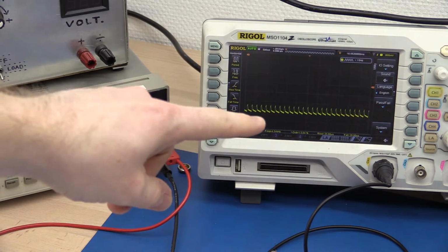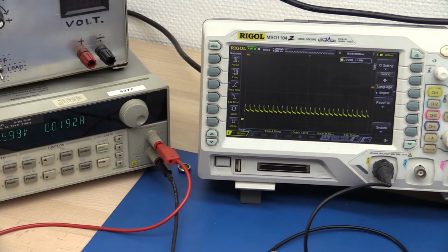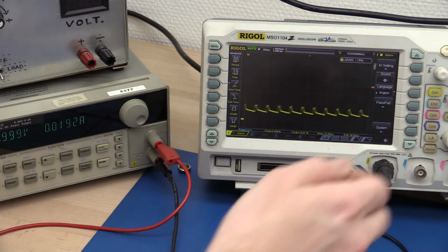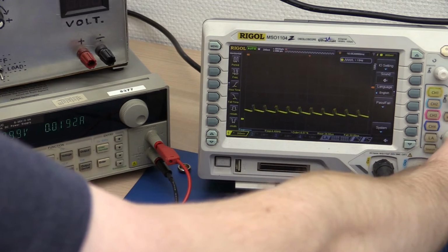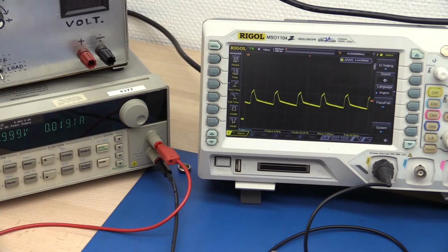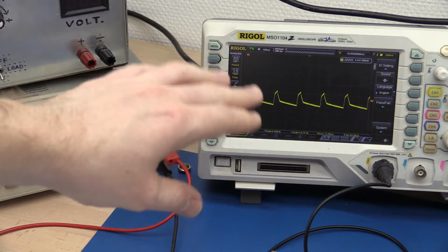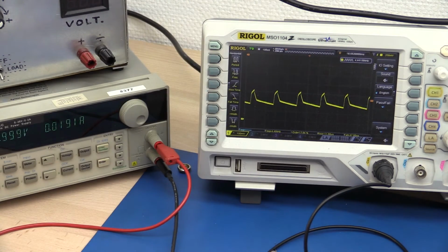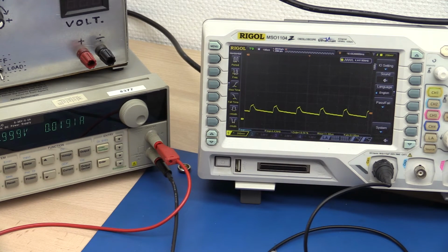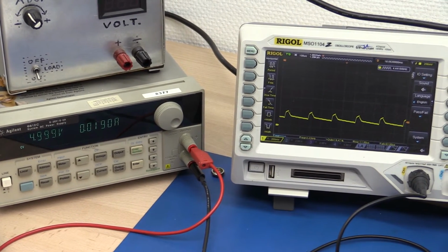And I'm measuring the output here, and we get a not so clean wave, but probably because it's made on a breadboard. We have the kind of normal looking switch mode regulator waveform here. It's just we have too much resistance, so there are a bit high ripples. Let's see if we can adjust the output current.